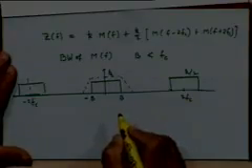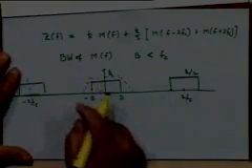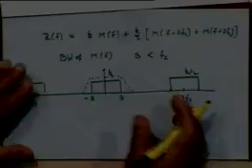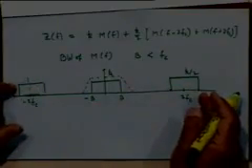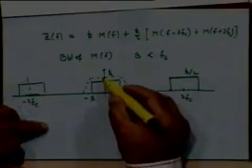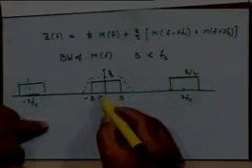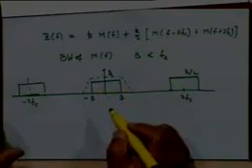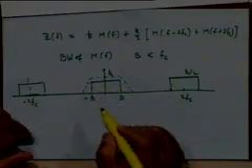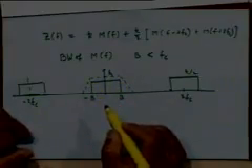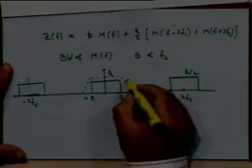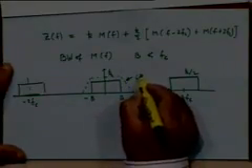You can correct it suitably. So if you have a low pass filter with a response like this, obviously these signals will get eliminated, and what you will get at the output is the product of this frequency response with this input spectrum, and therefore you will just get your M of f back. Is it clear? So that's the low pass filter transfer function.